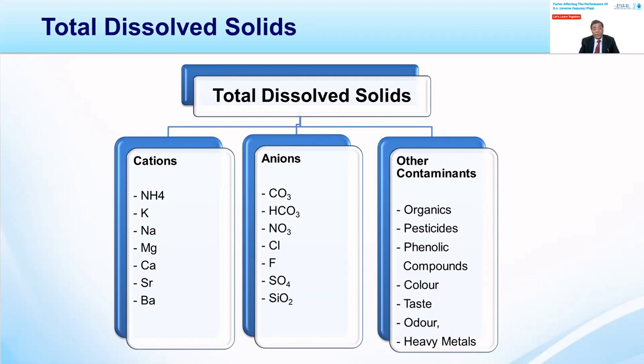and in the lab test report, we normally see what concentration of cations and anions is present in the feed water. And it is very important, whenever you seek to have an RO system or you implement the project, that you must have the complete water analysis so that you, or your system supplier, have complete data to design the pre-treatment and the RO plant based on the composition and the contamination of the raw water.